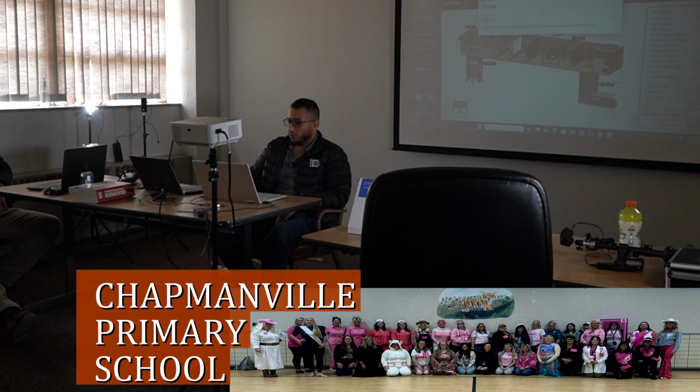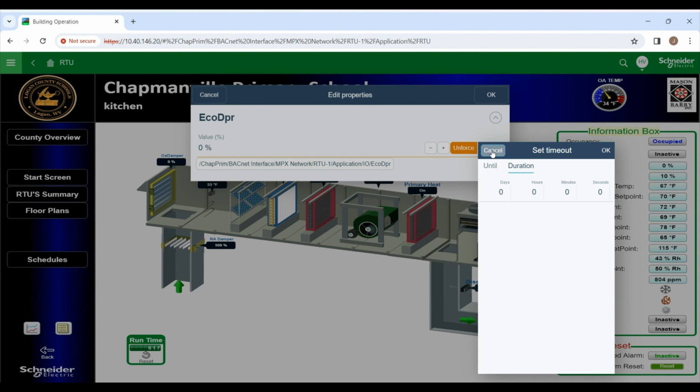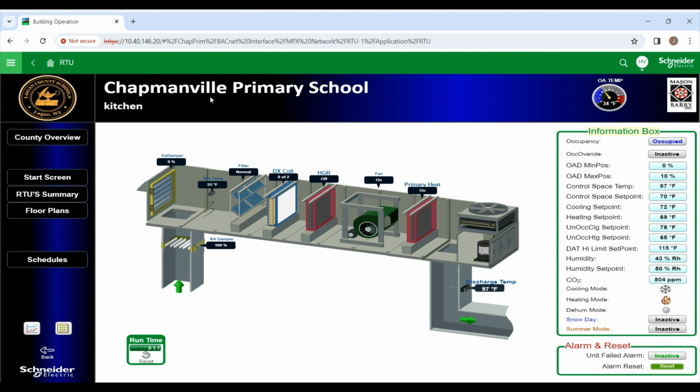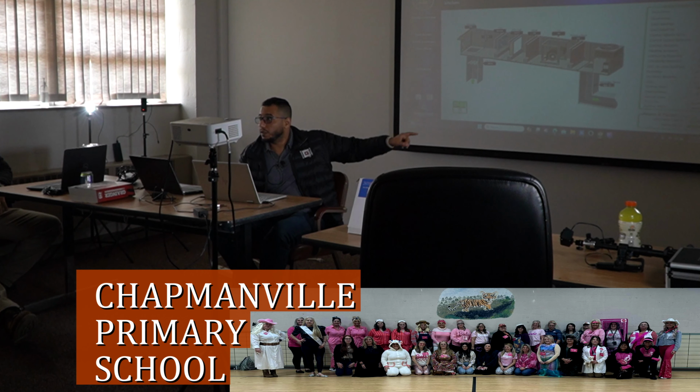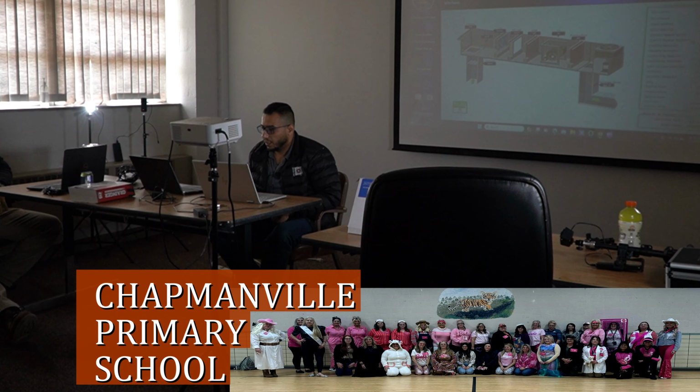Yeah. But show them over to the right there, because I can't see it very well, where the heating and cooling set point is. Just say you wanted to. Yeah, I was explaining that just a few minutes ago, but I will go through it again, because I want them to make sure they understand that. You can't just go to the heat and turn it up. You have to use the active set point.